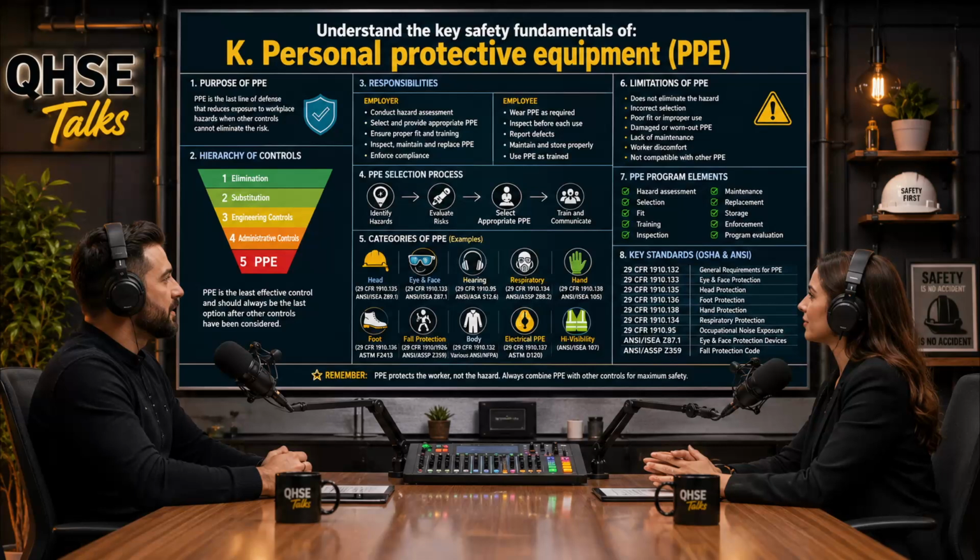Okay, let's do that math. So an NRR 30 earplug, you subtract 7, that's 23, divide by 2, that's 11.5. Right. It might realistically only offer 11.5 decibels of attenuation on the shop floor. So if your ambient noise is 105 decibels, that NRR 30 earplug is mathematically insufficient to get the worker down to a safe 85 decibel exposure. 105 minus 11.5 is still over 93 decibels. Exactly. In that case, you would need to implement dual protection, earplugs worn underneath heavy acoustic earmuffs.